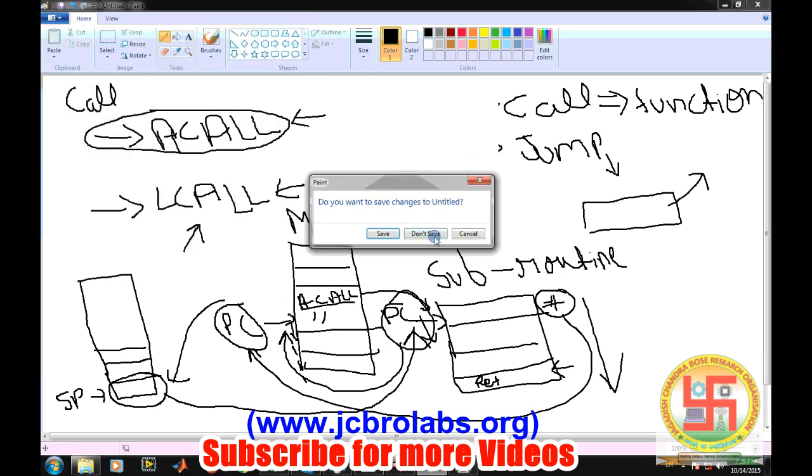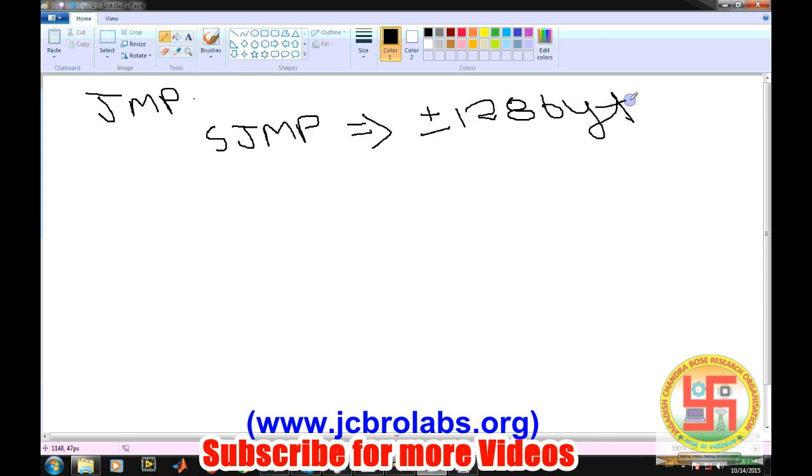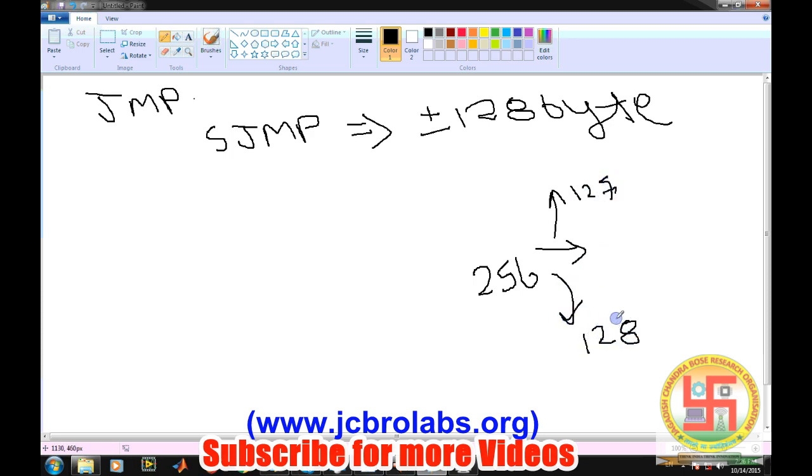Similarly, there is another instruction which is used for jumping, that is the jump instruction. These also create a jump, but in this case the address is not stored on the stack. So there are three types of jump instruction. SJMP, short jump. This is within plus or minus 128 bytes. Suppose this is the present location of the program counter, so it can go up to 127 bytes here and 128 bytes here.